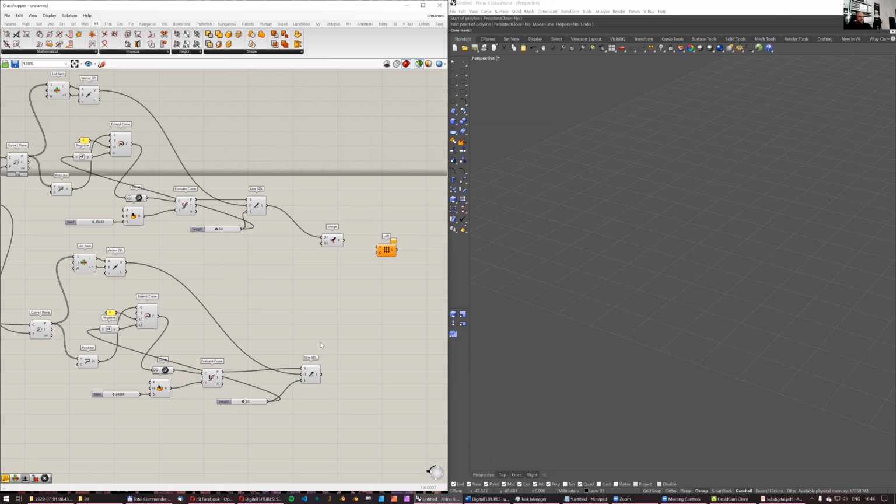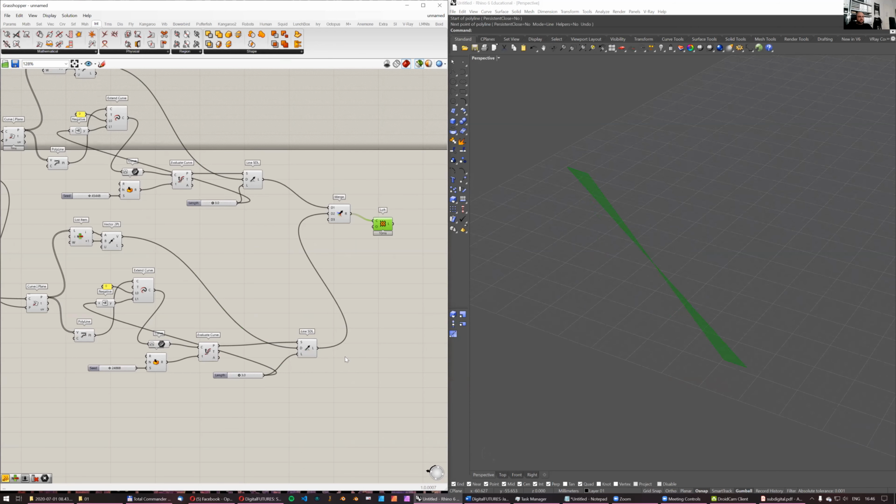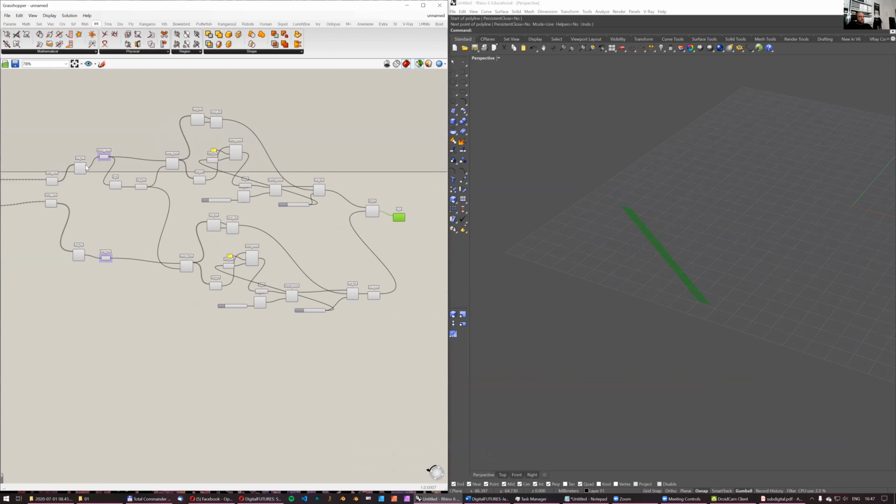Loft is a surface that is defined by its sections. So I've got 2 sections of the loft, and this is the result. I see that I need to flip one of those lines. Flip curve, this one. This might be a problem because that's kind of a random thing. So now I've got one of the legs. So you see that this is a valid leg.